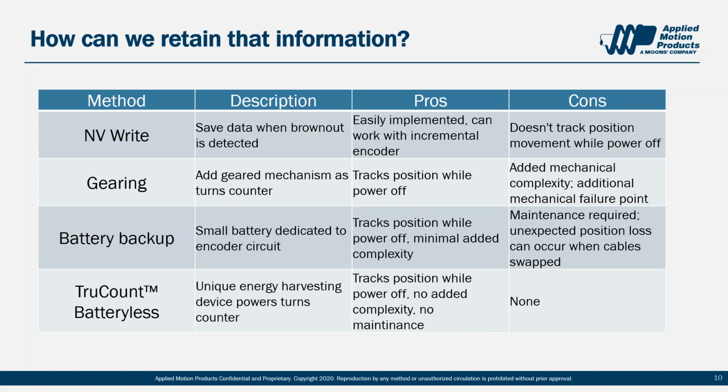Does the encoder require a second power supply? The encoder does not require a second power supply. It is completely and 100% self-sufficient. It harvests the energy. So this is a magnetic encoder. There's a magnet mounted on the shaft, and then there's a pickup coil that actually generates a pulse of energy on every rotation that powers the turns counter. So it's completely self-contained and self-sustained. Perfect.